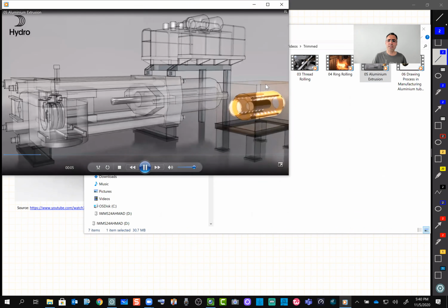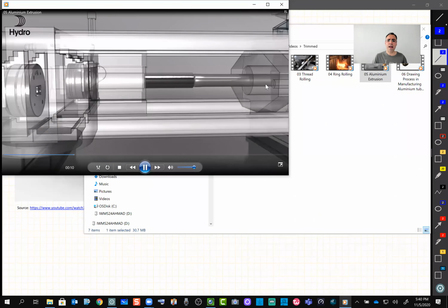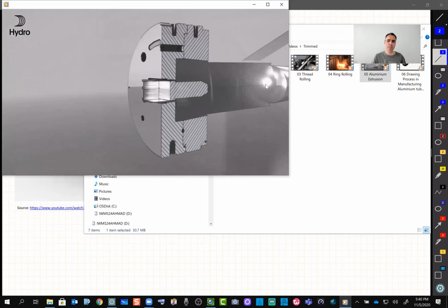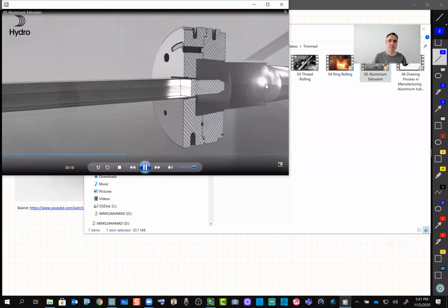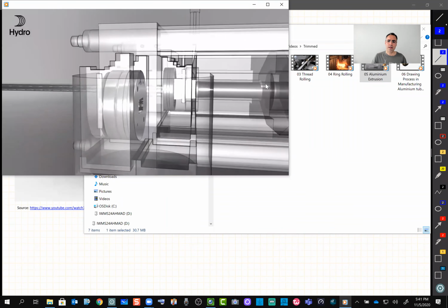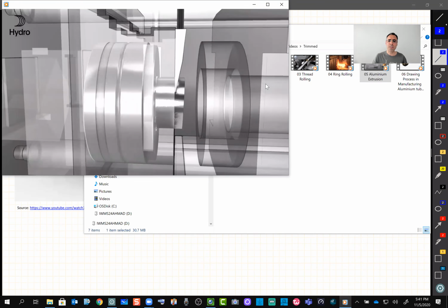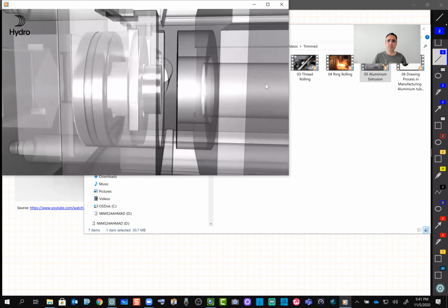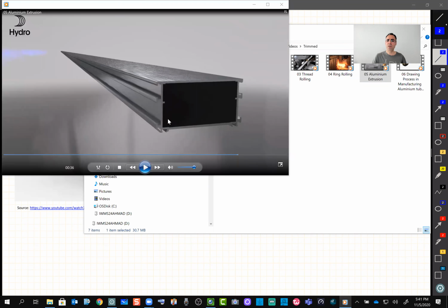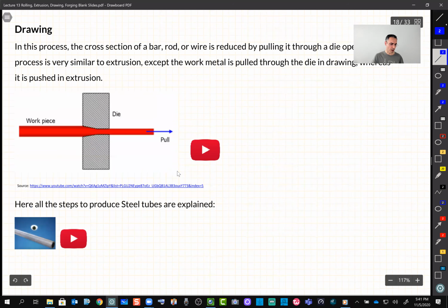In this schematic or cartoon, you'll see we have the billet going there and we push it into a profile. Here the profile is very simple, just a simple cross section. Obviously at the end, we need to trim the excessive material, and we get basically the cross section that we want. All right, that is extrusion, which is a very simple concept.